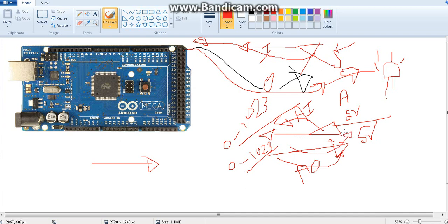You understand what I'm telling? Okay guys, the other way around it's going to work. So now you understand, right? Because you know these things, because we have studied it enough. But for example, if you are getting a 2.5 voltage, assume this is 2.5 guys, 2.5 voltage, this number is going to be 511. The serial printing analog input value is going to be 511. We know that, right? Because it is 512 unit.